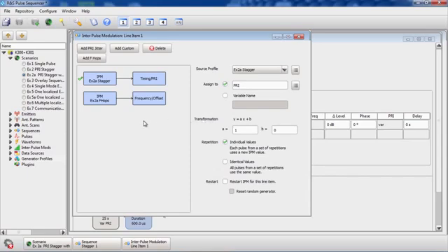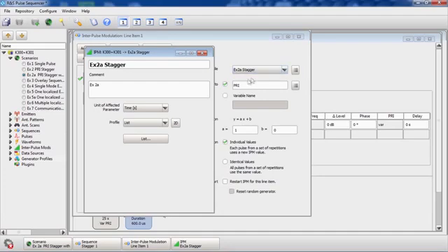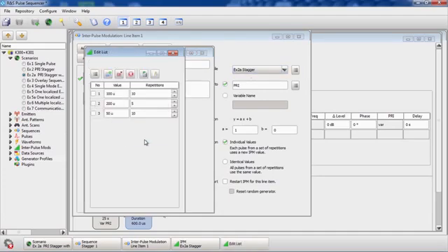You directly see that there are two different interpulse modulations used. The first one works on the timing parameter. The second one works on the offset frequency parameter. So let's see how the timing parameter is defined. You can do so by opening the dialog of the stagger, so to say the timing PRI parameter, and you see that there's a list behind. If you click on this button here, the list opens. There are 3 different values. These are the 3 different PRIs that are being used.